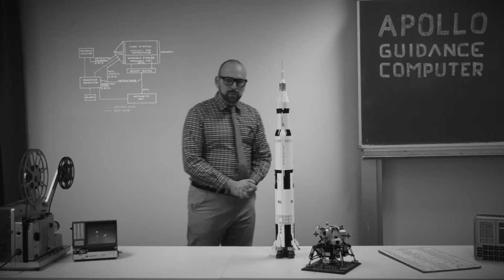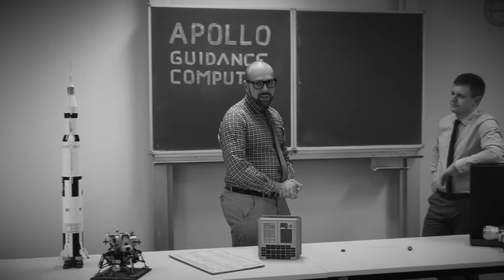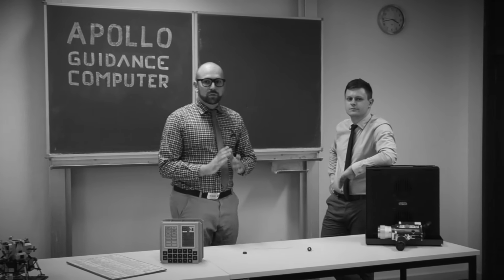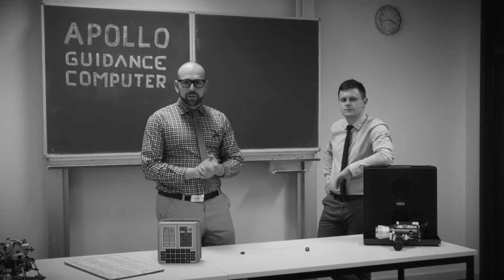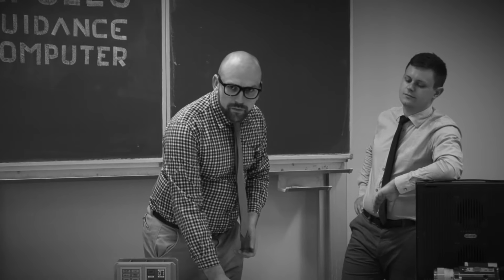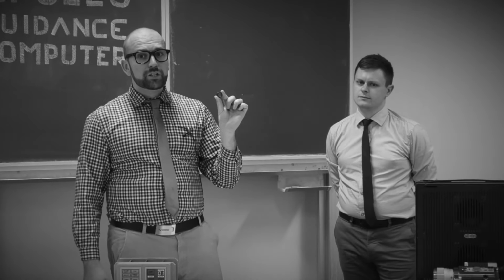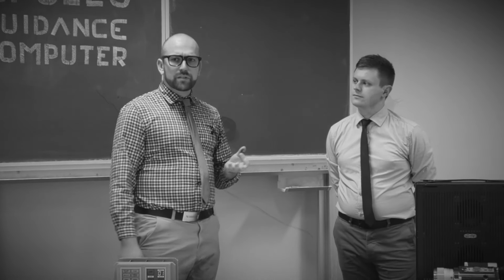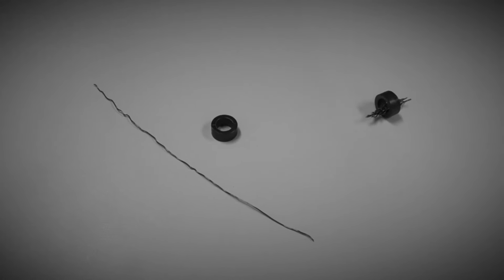The Apollo Guidance Computer Random Access Memory, short RAM, is built the same way as in today's modern computers, magnetic core memory. Let us take a brief look at how this works. The memory is made of an array of magnetic cores, which can be magnetized and maintain their magnetization, even when there is no magnetic field applied. This means a magnetic core memory keeps its information even in case of power failure.